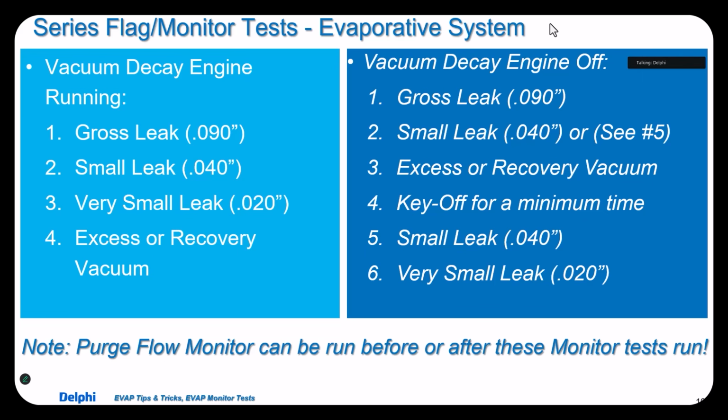And if you ever check this, you'll see that that first one runs a lot when the engine's cold. As the day warms up and you drive it more, it won't run anymore that day. But if it gets interrupted anywhere, it's got to start the whole sequence all over again. EVAP is a series monitor. We either do them all in one key cycle or we don't. And we start fresh each time, even though there may be numbers stored in mode 6.